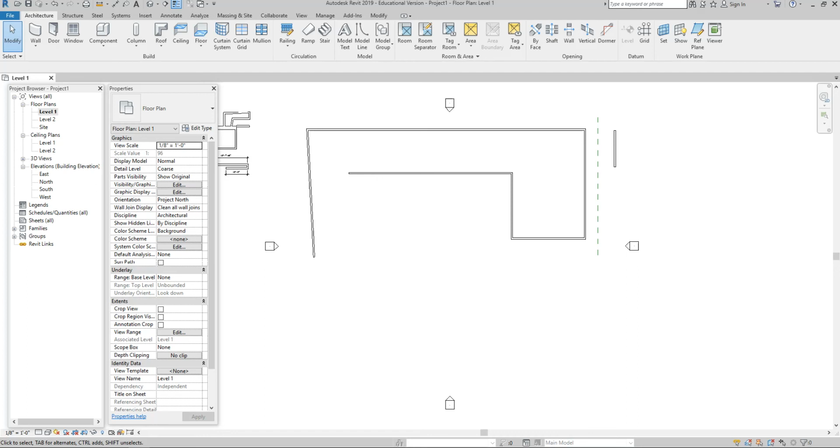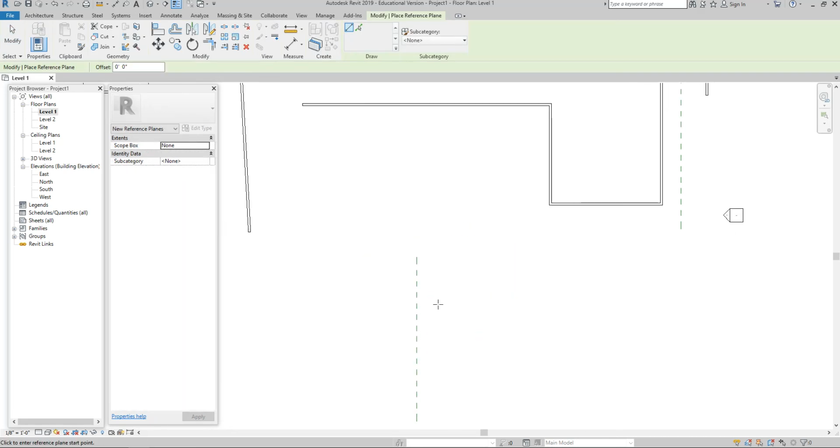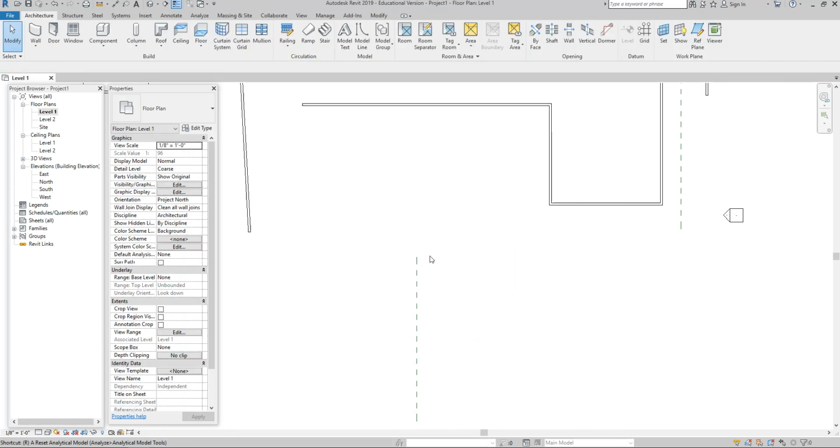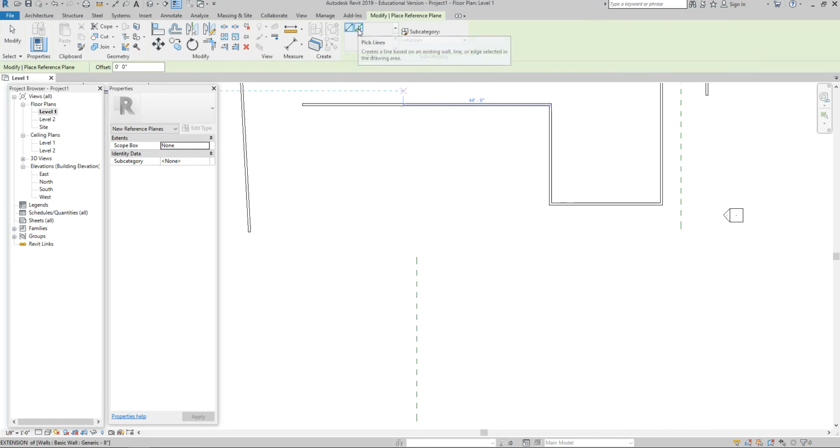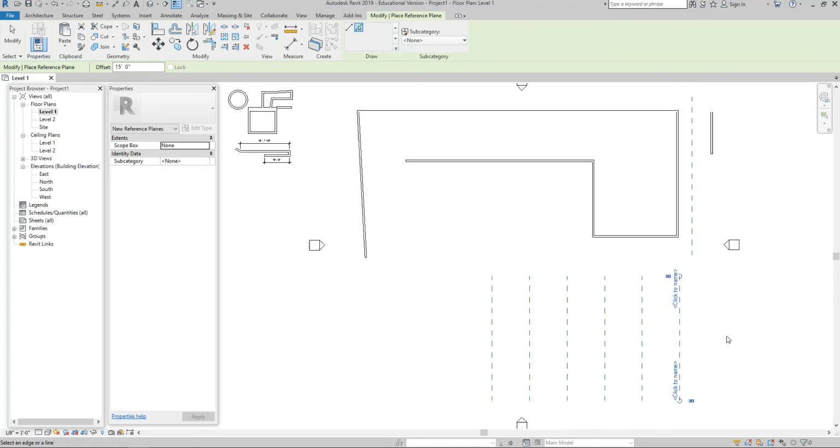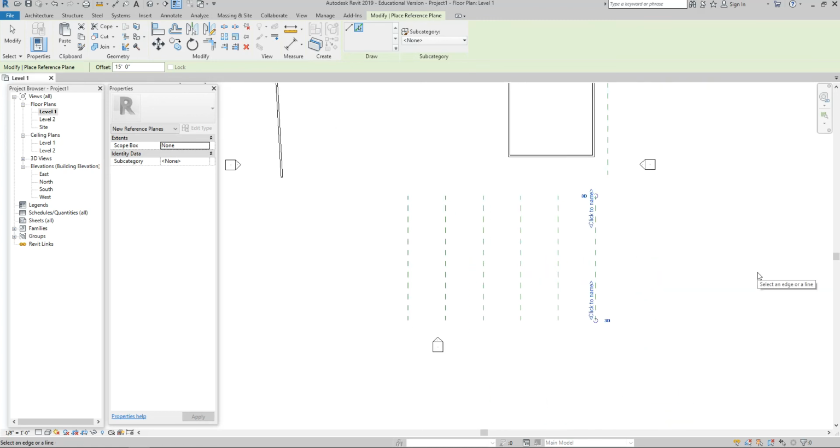All right. Any questions so far? Yep. With the reference planes, can you offset them just like you did with the walls? Yes, absolutely. So if I'm trying to visualize a structural grid and I do RP, right? And I'm like, oh, I think that it probably needs to be about 10 feet. I can type RP and choose pick, right? Because I can draw them with a line or a pick, and I could offset it like 15 foot, enter, and I could just start saying, well, yeah, that looks like it'd work pretty well. That aligns with this or that. So I can, absolutely. Yep.